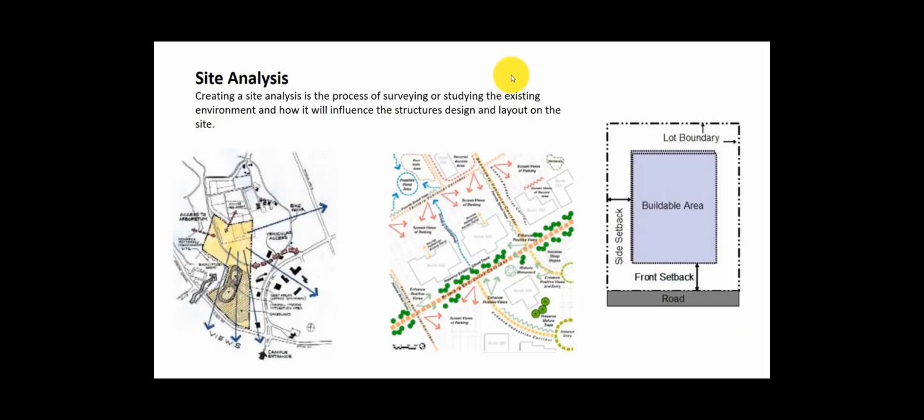The site analysis is important because you secure a site and you need to know everything about that site before you start designing. And so the site analysis is really graphics that help you to analyze things like the views and the sun angles and the noise, the winter winds and the summer breezes, and so many other things that we're going to be taking a look at, like vehicular access, where do people walk, where are the utilities, all of those things that you would need to explore.